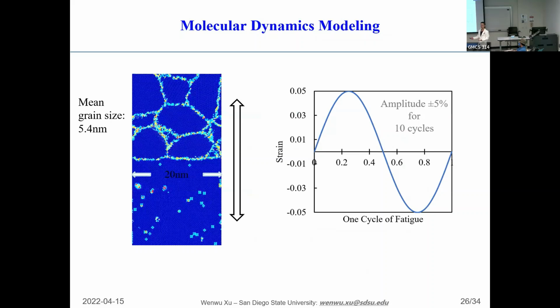Right, and of course, we cannot simulate the entire model, it's just going to be too big. So we will only be able to simulate a tiny small section. Imagine this would be a part of the network of the nanocrystalline structure, and this would be the grain interior coming from that large grain. Then we would like to apply some fatigue testing and track the dislocations to see what is happening in there.